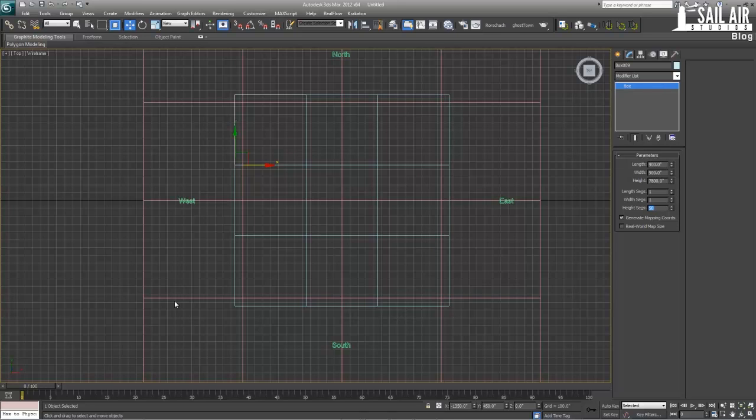Next, the southeast, southwest, and northeast towers, so this one. And these are 66 floors. So 66 segments. We're just making a floor segment because it's easy to work with when we snap it. Next, what we will have is the 90 floor segments, which will be the southeast and north towers. So these are 90 floors tall. So we turn our height segments, make them 90. Turn east, make it 90. And turn on our south tower, make it 90.